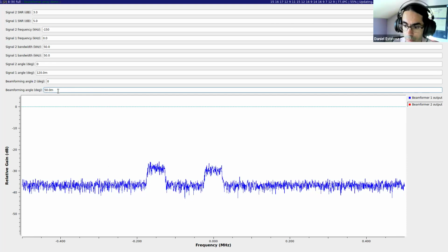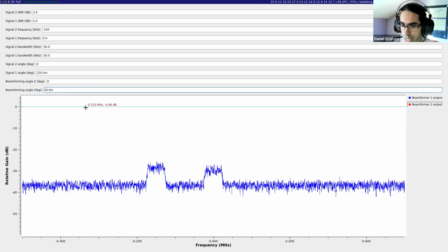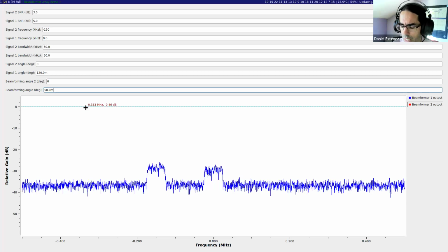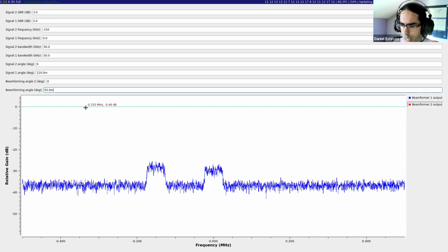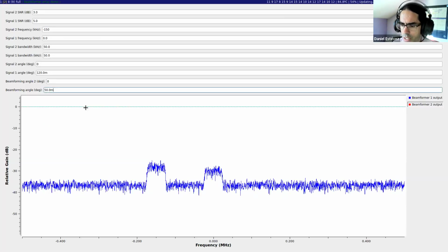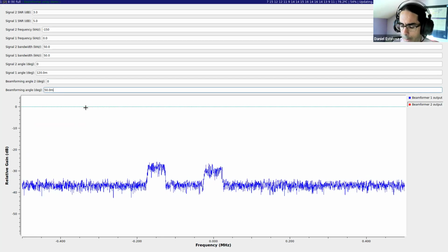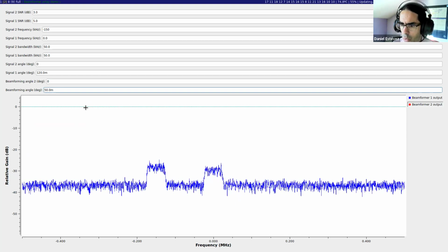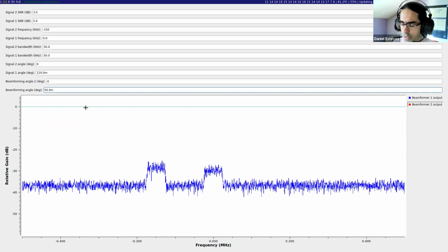And in real life, I would make this with 2 variables because the sky is a plane and it has 2 variables. However, if we want to have one beamformer for each pixel in the image, that's going to be very computationally intensive. So you can think of this UV plane, FFT, and so on and so forth as a way to have a beamformer on each pixel of the image, but in a way that uses FFTs to be much more mathematically and computationally efficient.